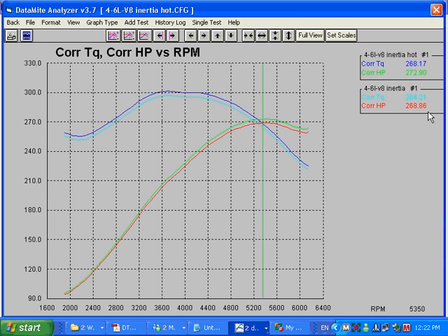And you can see 68 versus 73, or 69 versus 73, about a 4 horsepower change from 14 degrees of temperature change. What that means is if the temperature you're reading, air temperature, is in error by 14 degrees, you're off 4 horsepower for this case, which looks like about 2%.